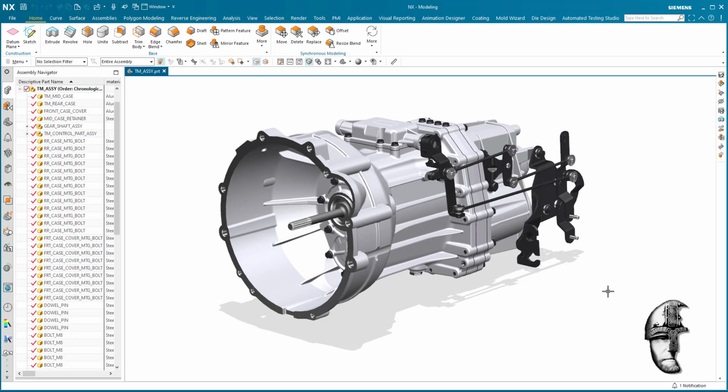And I would start by sectioning this. For sectioning this, we have the radial pop-up buttons. So if I, for instance, use the right mouse button, if I hold that down, I will get the radial that is under there. And the thing I'm after is the clip section here. If I drag and release on the clip section, it's going to create a section here, or show the section. And if I do it really quick, you won't be seeing that, but the section will turn up.